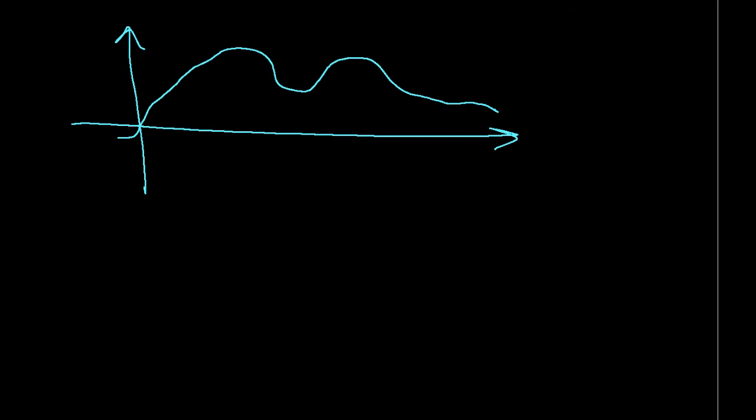By using Fourier analysis, I can determine how many samples of the signal I need to represent it accurately in a computer. A sample is basically looking at the signal at a particular point in time and taking its value and quantizing that. Fourier analysis lets you compute how many samples of the signal you'll need in order to be able to reconstruct the signal at a given degree of accuracy. This is extremely important because in order to process a signal in a computer, you have to have samples. Computers don't operate on continuous time signals. You need to take samples and then convert them into bits.